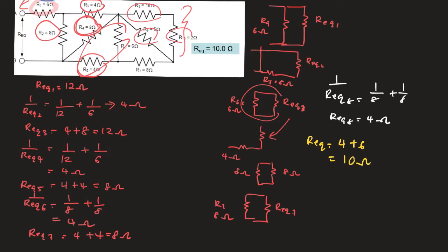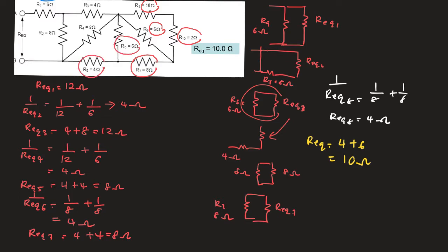Okay, so you can actually see that the arrangement of this is series, parallel, series, which is alternate. If I conclude this to make it simple for you, the 10 and 10 here is series, parallel with the 6 ohm, and the combination of this is series with the 8 ohm here, and this combination is parallel with the 6 ohm, series with the 4 ohms here, and parallel with the R4 here, and the combination of this is series with the 4 ohms and parallel back with the 8 ohm, and finally series with the 6 ohm. Okay, so this concept we call the alternate method.